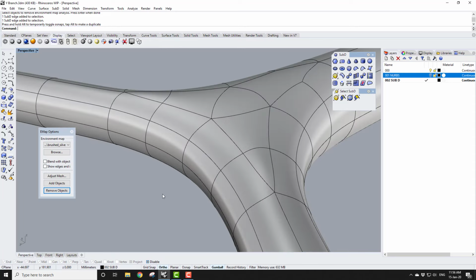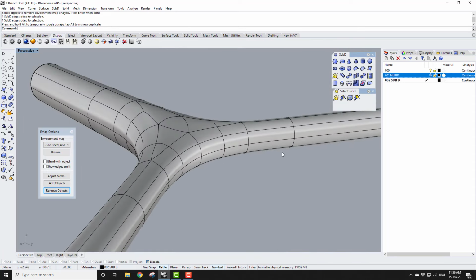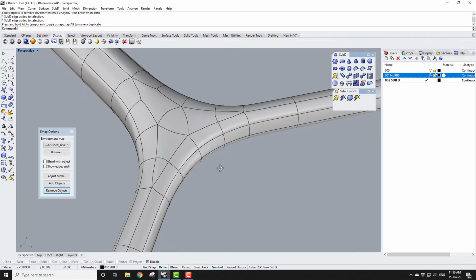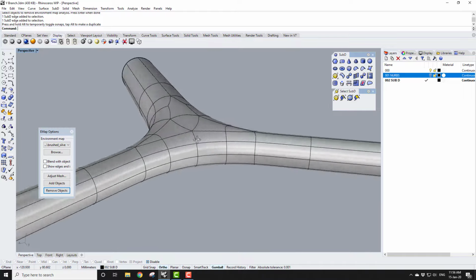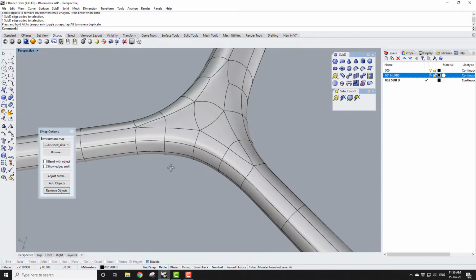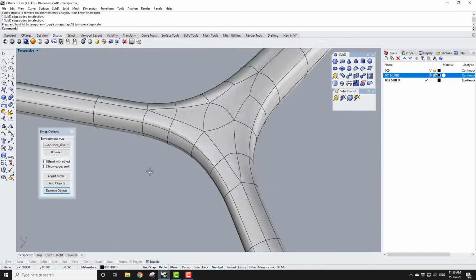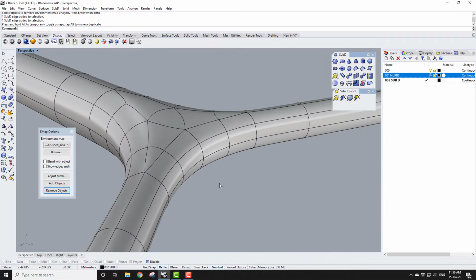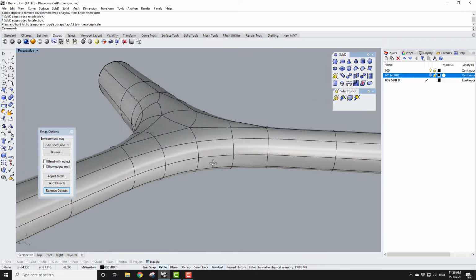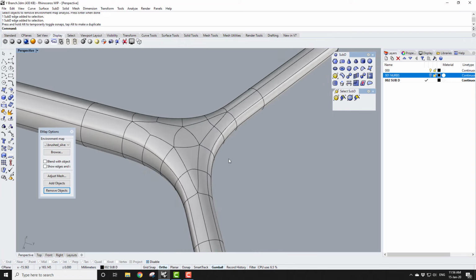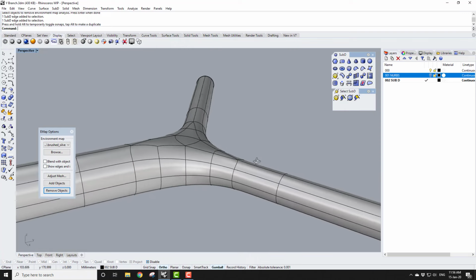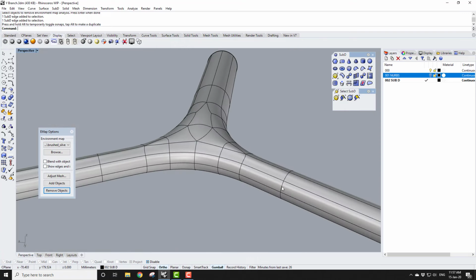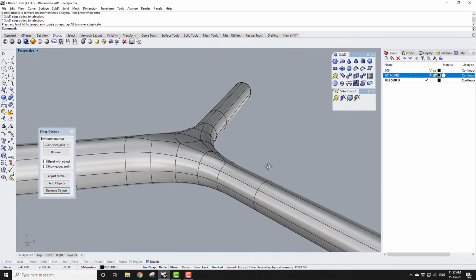So the whole idea behind this SubD surface is that it's intrinsically smooth, so it's analogous in some ways to a degree 3 surface. So it's intrinsically smooth for curvature continuity, unless of course we specify any creases. So all I need to concern myself with here is the shape of these objects. I don't need to concern myself with the smoothness unduly.